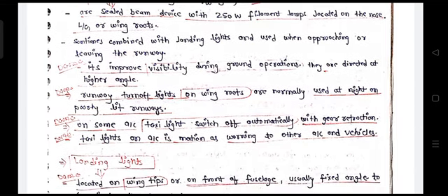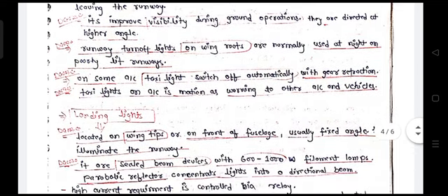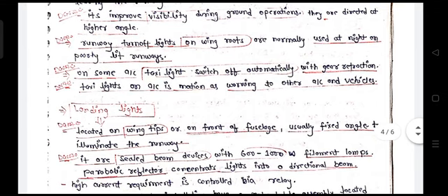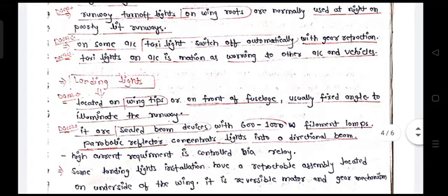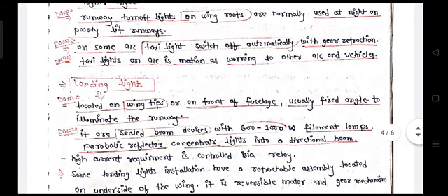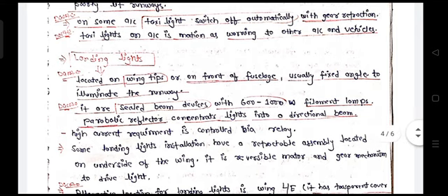Now, 250 watt filament lamps are used. This is one most important thing. It improves the visibility during ground operations. Taxi lights are basically used when the aircraft is taxiing with its own engine power, moving on the ground. At that time it increases visibility a lot. Runway turn off lights are on the wing roots in some aircraft, and in some aircraft they may be on the landing gear also. It is automatically switched off with gear retraction.